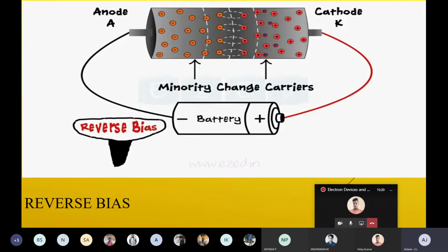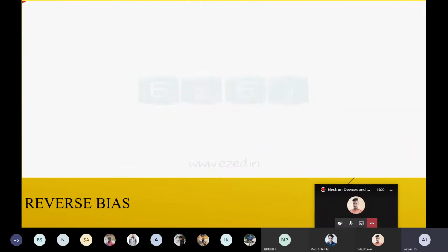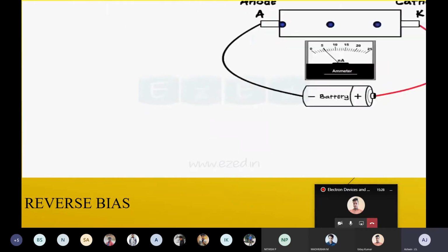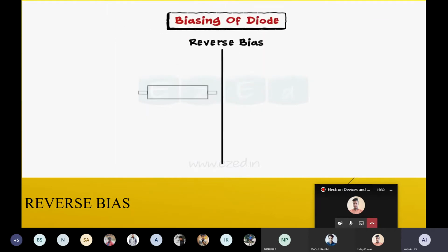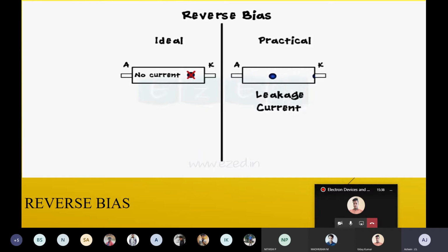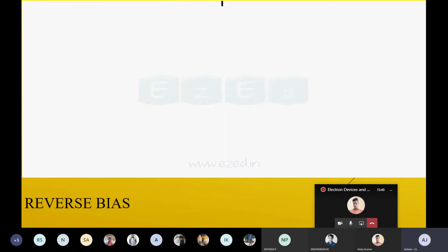So what is the difference? How is it getting the energy? In a reverse bias condition in avalanche, by giving the excess field, I'm giving more voltage, 20 volts, right? The immobile electron gets sufficient energy to come out of the covalent bond. That's why we are able to create a lot of free electrons after giving high voltage. So the breakdown will always occur at high voltage.